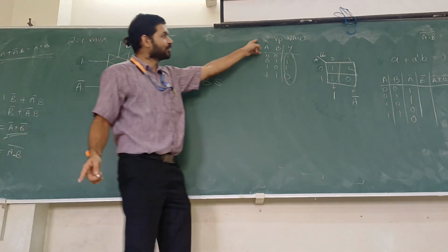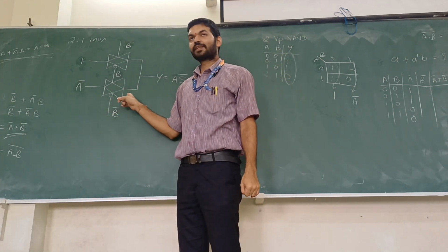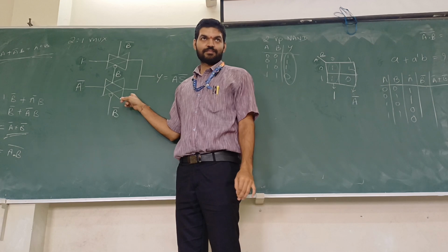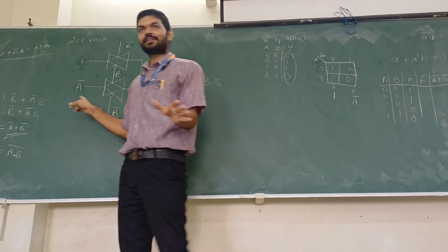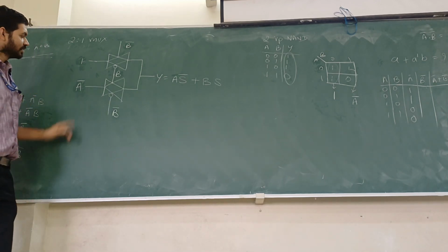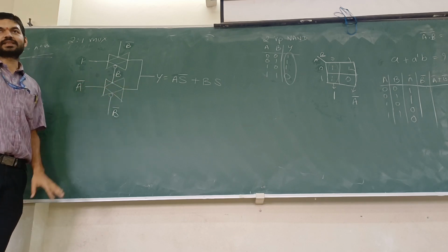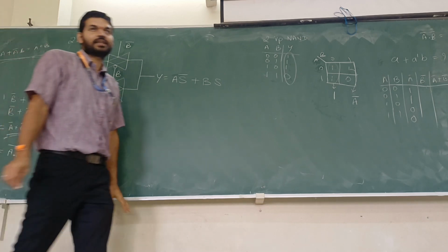We started to design NAND gate and we have designed NAND gate using TG. So except inverter, except NOT gate, everything can be designed using TG. Because TG won't invert the signal. TG will pass the signal as it is. Therefore, we can't design the NOT gate.